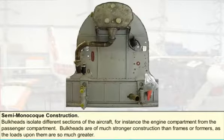Bulkheads are set in place to separate the different sections of the aircraft, for instance the engine compartment from the passenger compartment. The bulkhead has the same basic shape as the frame or former, but almost completely isolates one compartment from the other. Having said that, some holes will have to be made in a bulkhead in order to allow control fittings, pipework, and electrical cables to pass through.